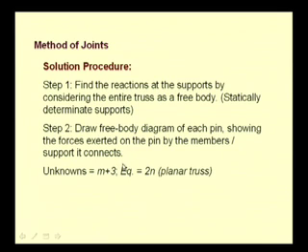Here we will see that for a plane truss, if we have m number of members, then we have m number of unknowns plus 3 number of external reactions to be determined, and the number of equations from the n joints will be 2n, and thus for the problem to be statically determinate, m plus 3 should be equal to 2n. In 3D, we see that the force summation equation at each joint results in 3 scalar equations. Thereby, we can determine 3 unknowns for each of the free body diagram from the joint.